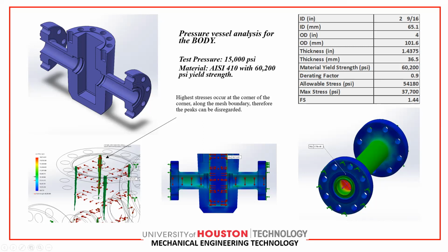That is shown here. This is the inside of the gate valve, which has 4 corners, and all the high pressures occur at these edges, 1, 2, 3, 4. This red color shows where the fluid is affecting the valve body. These arrows are the internal pressure that comes from the fluid passing through the valve body.